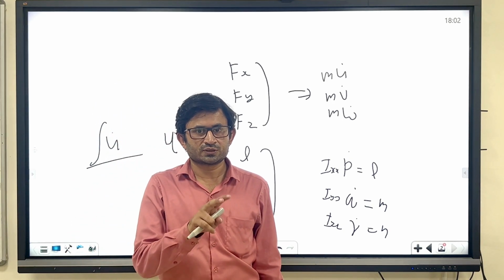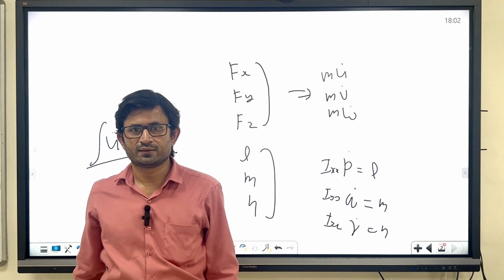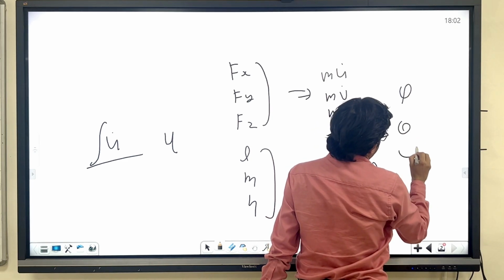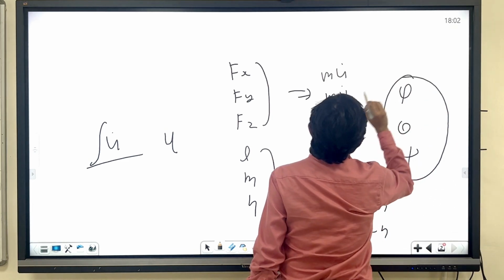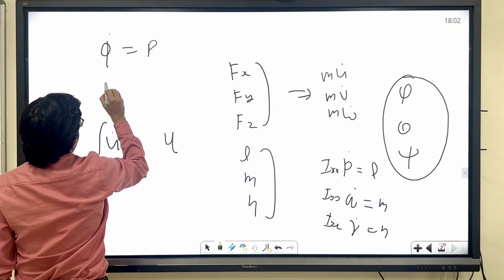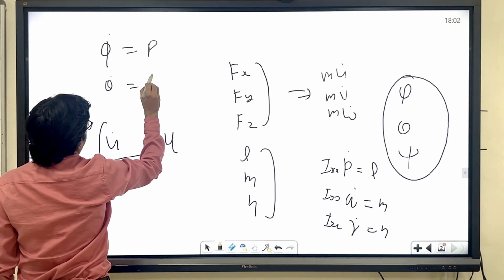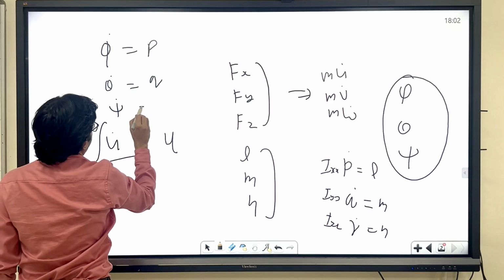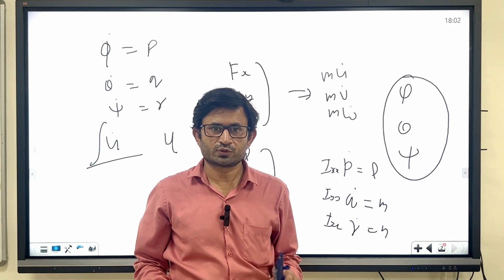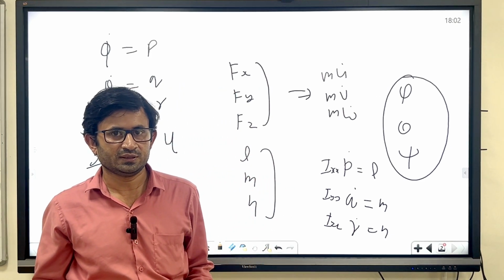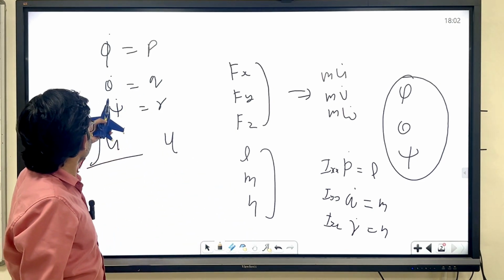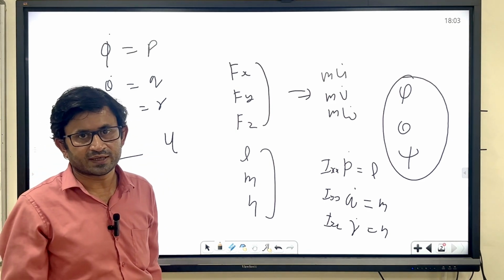Okay. So, from this 3 rotation is called Euler angle, phi theta psi. Clearly you can see that phi dot will not be equal to P, theta dot will not be equal to Q, and psi dot will not be equal to R. There will be a rotation matrix. That rotation matrix I will also discuss in the flight simulation course. Now, if you integrate phi dot, theta dot, psi dot, you will get the attitude of the aircraft.